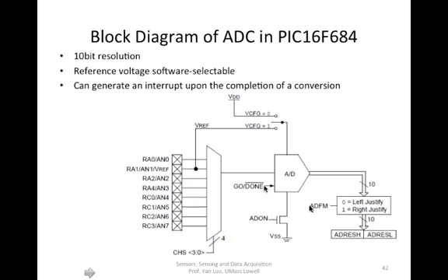This idea applies to many other options you're going to choose while doing this ADC conversion. For example, here you can use VCFG. This is 1 bit from a control register, the ADC control register. If you put 0 on this bit, it's going to select VDD, the supply voltage, as the reference voltage. So your input voltage you're going to compare with this VDD. If you put 1 on this bit, it's going to use the external reference as the comparison reference. So you can do that by setting the proper value of this bit.